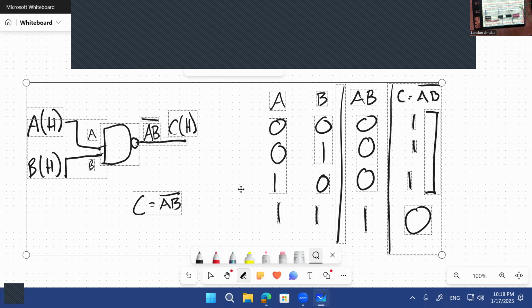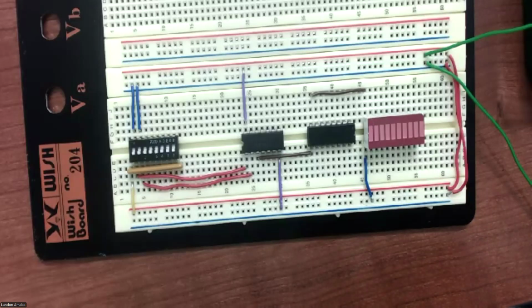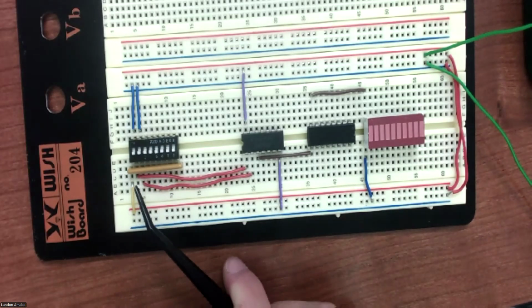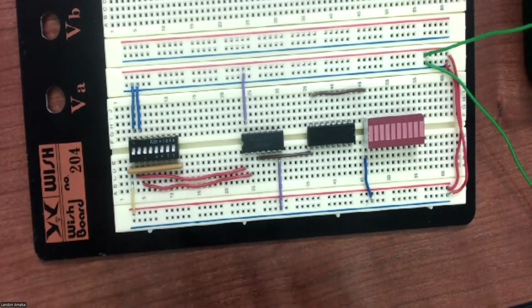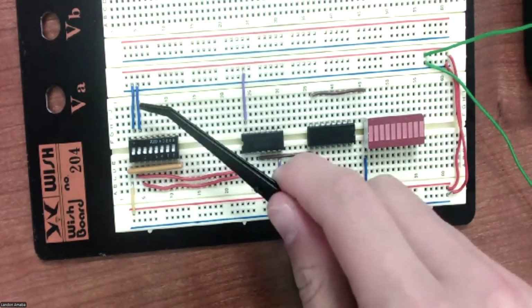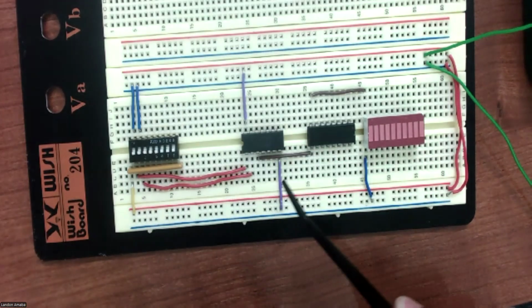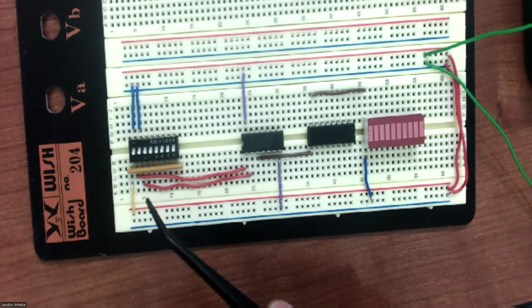All right, so now I'm going to go back to our circuit and we'll do a quick overview before ending this video. So some important things to note, this SIP resistor, it's very important you have the black dot on the left side and these two sides connected to ground and your signals coming from this resistor side.